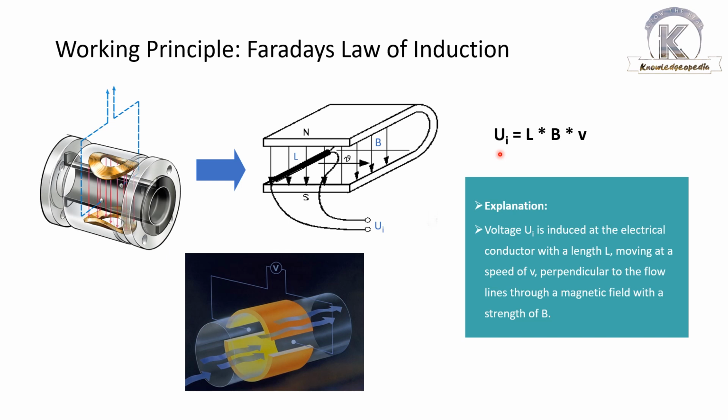If you multiply it by 3600, that converts the per second value to a per hour value, which represents the meter cube per hour value. So if it comes out at 200 meter cube per hour, that means after an hour a totalized volume of 200 meter cube, that is 200 kiloliter, of water or liquid will have passed through. That would be the totalized value. Simple. If the flow rate is 100 meter cube per hour, after an hour the totalized value would be 100.